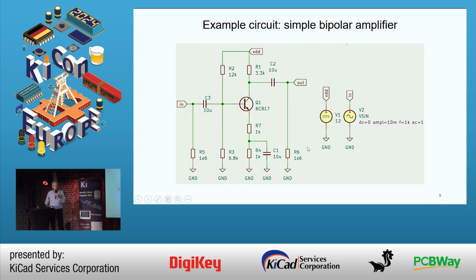And there is one thing specific to the simulation itself: the simulator, of course, needs to know what kind of voltages you put onto your circuit. Therefore there's a special library part, the simulation SPICE library, which offers these devices as a DC voltage source or an AC voltage source, and these are coupled via the global tags into the circuit.